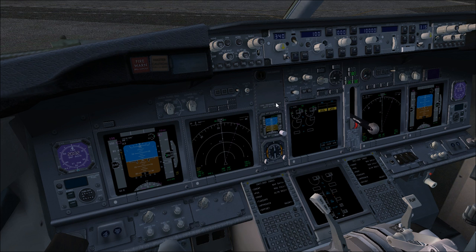Now I've said everything I can about the EFIS control panel, and I will show you other information. In case one of the display units fails during the flight, the DU system works automatically to reselect the proper selection of displays inside the airplane. If you maintain these 2 switches that control the display units in the normal position, those displays will be reselected automatically in case of failure of any of the display units.